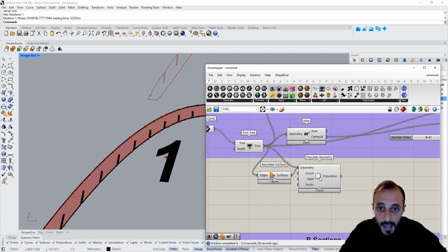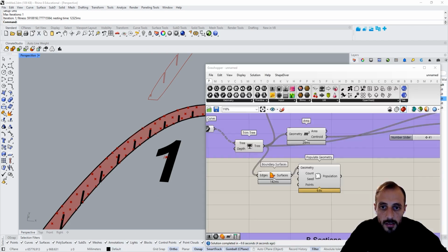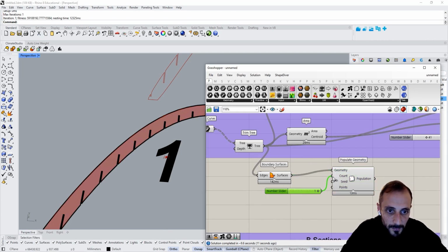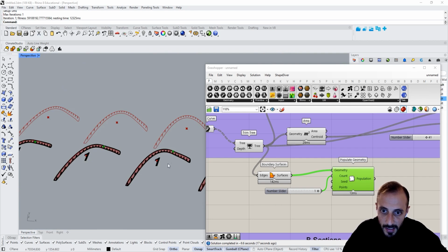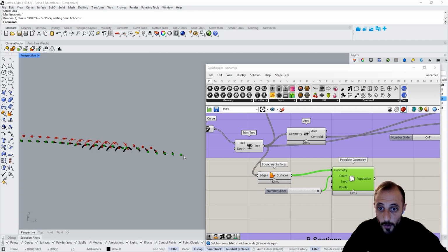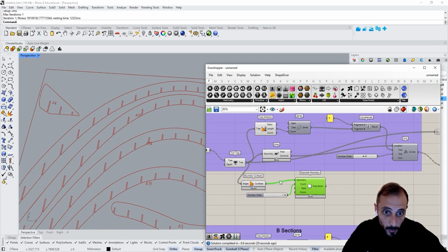Populate geometry, and then instead of populating 100 geometry, what we can do, it's taking a bit of a time here. You see, instead of having a 100 geometry per each surface, we can have 1 point only. This will make things a lot faster and easier. You see now, every point that I'm creating is inside of these pieces. Therefore, we were not going to see my text that are floating all over the place.